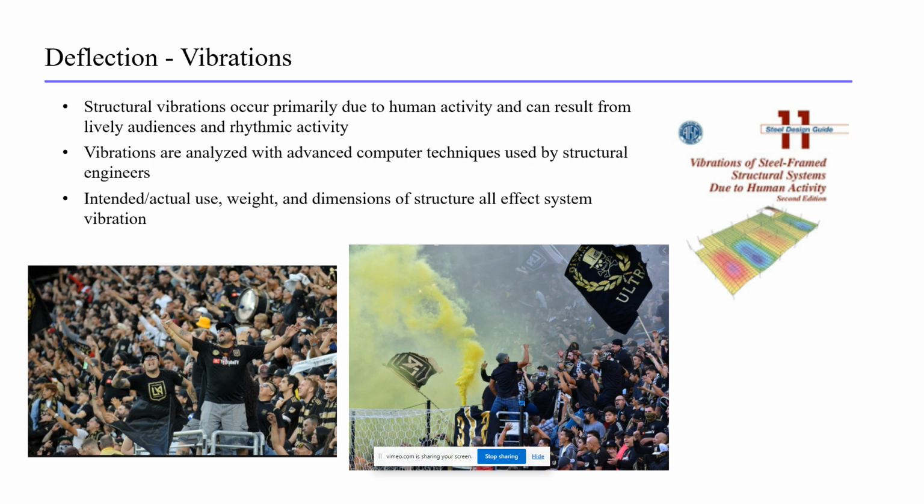The durability of system components can greatly affect the performance as well. Materials that are appropriate for the environment should be selected. Wear surfaces should have appropriate durability for use. Aluminum or stainless is best suited for exterior environments, for example. And walking surfaces should be made of a material that is resistant to scratching, has adequate surface features to prevent slipping. In addition, you should think about the system fastening and operation. If you have fastening devices that are very difficult to use or that may get damaged over multiple uses, you may not want to use those. Demountable system contractors should be consulted regarding system features, setup and strike instructions, things of that nature.